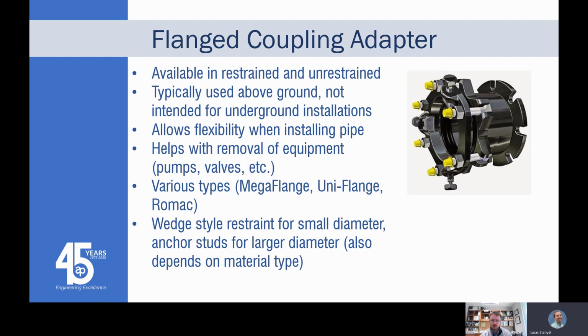over time blew the flange coupling adapter off. And after we found it, you could see that every time that air pocket went through, it pushed this up on the pipe, a quarter inch or something, until it finally got to the end of the pipe and blew off and made a mess. Made a big mess, Old Faithful. Yep.